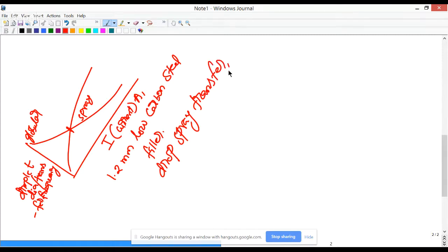In this case, you have a droplet detached from the electrode tip with a diameter equal to the filler diameter. You also achieve a reasonably high frequency of transfer compared to globular transfer, and the droplet diameter is smaller than what you detach during globular transfer. The main transfer force that aids the transfer upon spray transition is the Lorentz force, the electromagnetic force. Because you can achieve a high Lorentz force by increasing current, you can detach a droplet of smaller size, aided by the high Lorentz force. So when the current is increased just above the spray transition current, you have drop spray transfer.